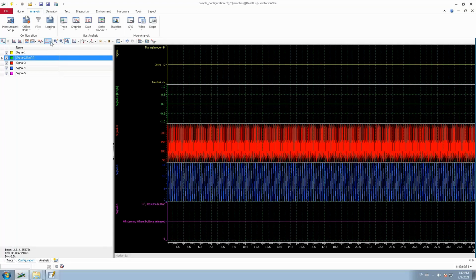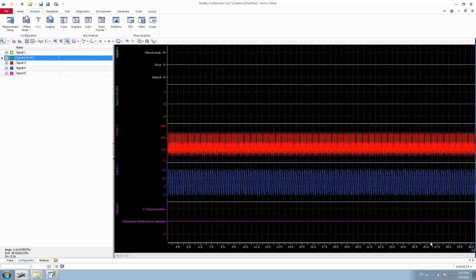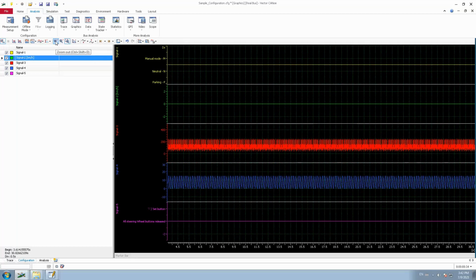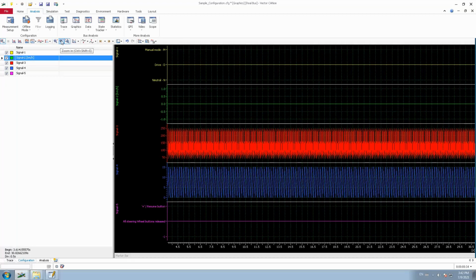If you want to do the zoom in and zoom out based on the y-axis, then you have to select the y-axis, and all your zoom options will be tuned to the y-axis. So when you zoom in or zoom out, your x-axis will not change. Just make a note of it. You can see it's 30.5 here, and when you zoom out there is no change in your x-axis, but your y-axis keeps changing based on your zoom in and zoom out options. So that's how you could make use of this scaling mode. The third option that you could select is adjust all directions.